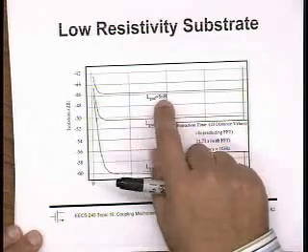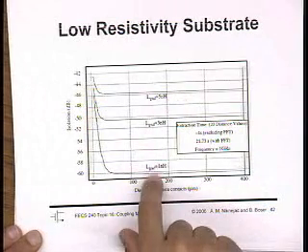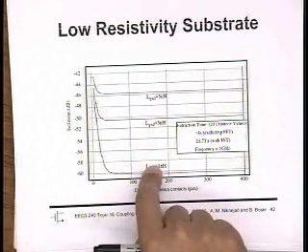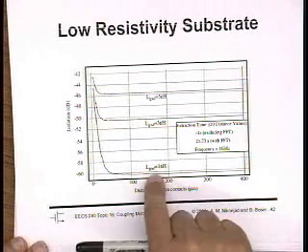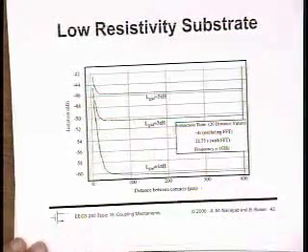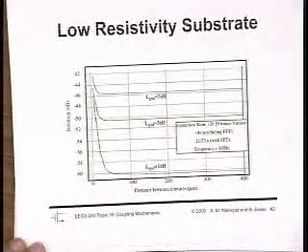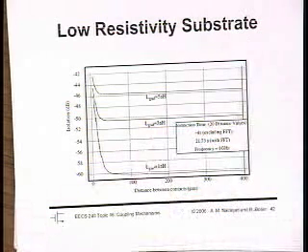So if you go from 5 nanohenries down to 1 nanohenry, then you're increasing your isolation from 40 dB up to 60 dB. And kind of a back of the envelope number that I carry in my head is, yeah, I can get 60 dB of isolation because I can put a good ground on my backside. And so usually package coupling will then dominate. Package coupling, if you're not differential, could be as bad as 30, 40 dB. If you go differential, you can probably bring that up to 50, 60 dB, in which case both effects are important. So if you have an amplifier with more than 60 dB of gain, potentially you're in trouble because the substrate and package isolation is less than that.